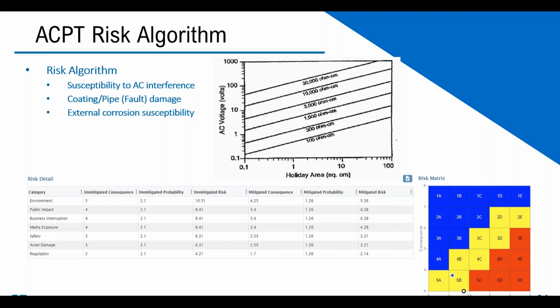But then that's a desert area. But at the same time, in that same desert area, you come in and you got a saltwater table, then all of a sudden it comes up, and it's 30 ohm-centimeter. So you could go from 8 or 9 million ohm-centimeter down to 30 very quickly, and then you wonder what happened.